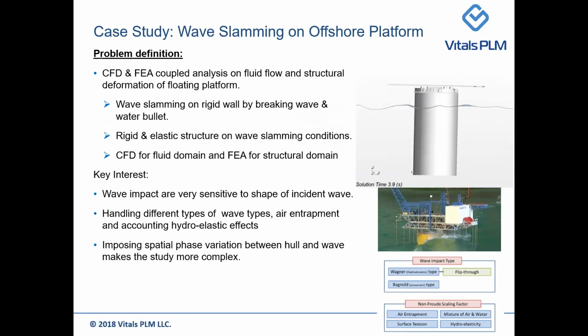The key interests are that wave impacts are very sensitive to the shape of incident waves, and handling different types of wave types, air entrainment, air entrapment, and accounting for hydroelastic effects, and imposing spatial phase variation between hull and wave makes the study more complex.